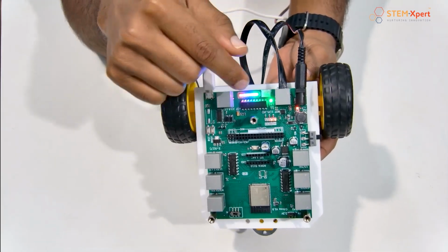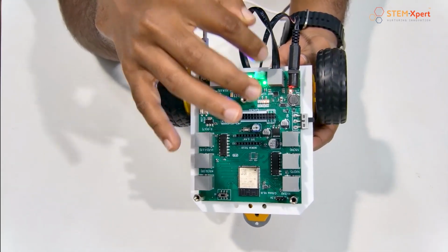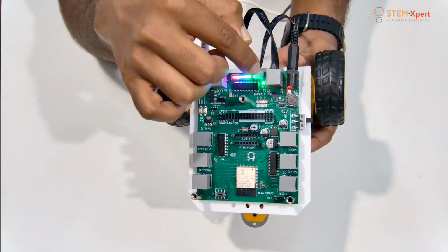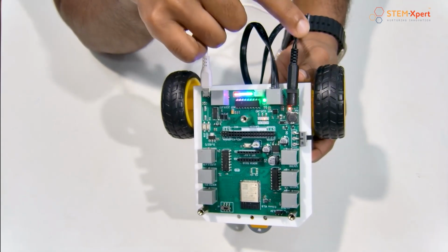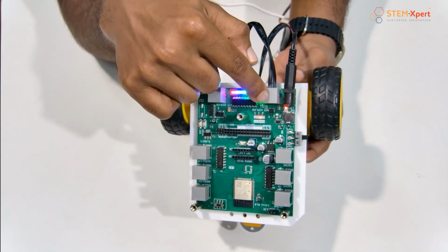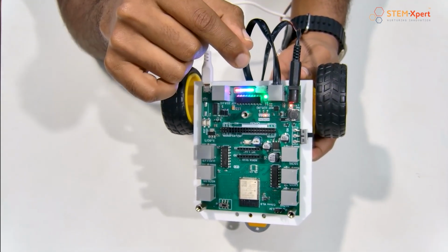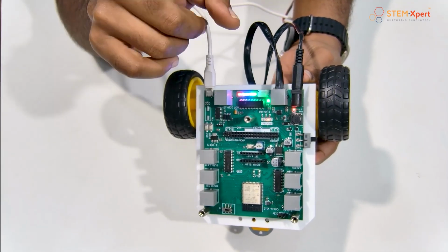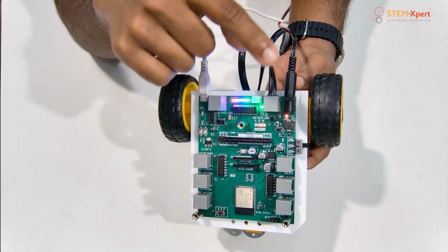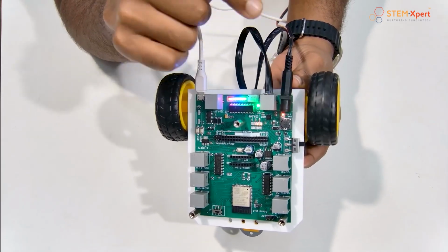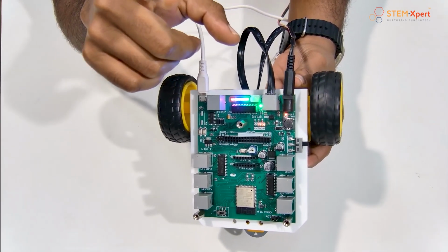It is because these LEDs and motors are connected with each other and it is now connected to the 25 and 26th pin. The motor is moving because the 25th pin is now getting a positive voltage for the first 1 second and then it will be turned off for 1 second. So that's why it is moving forward and stopping for 1 second, right?